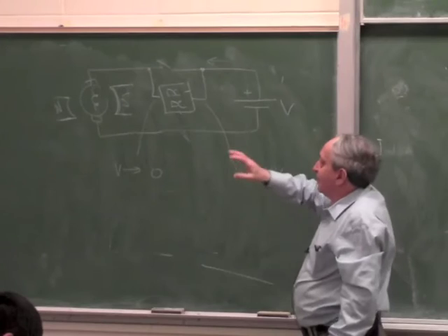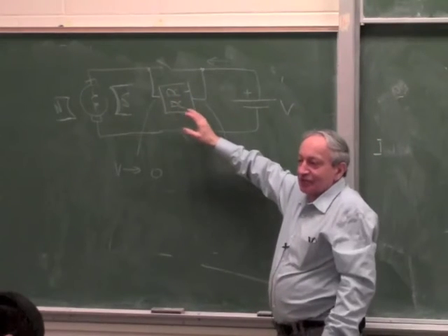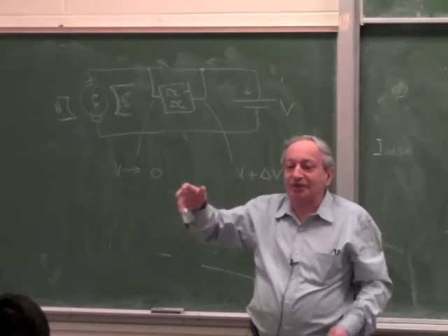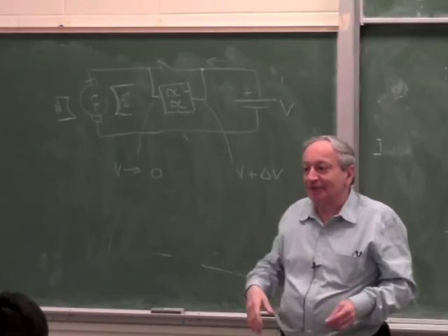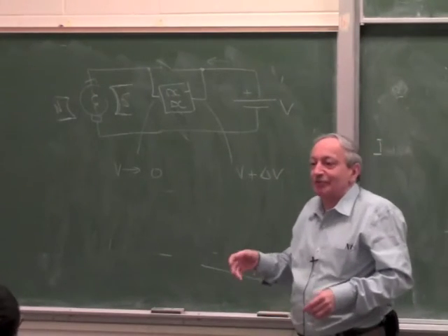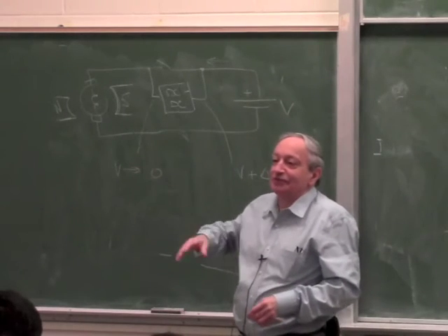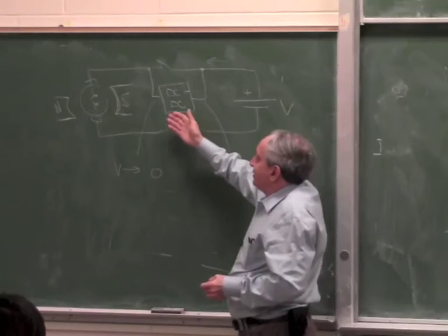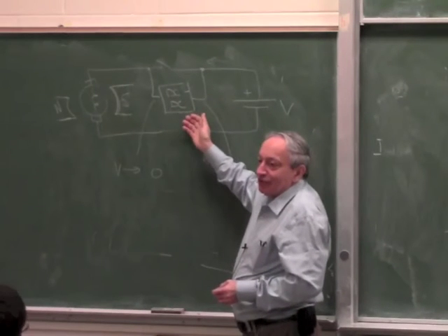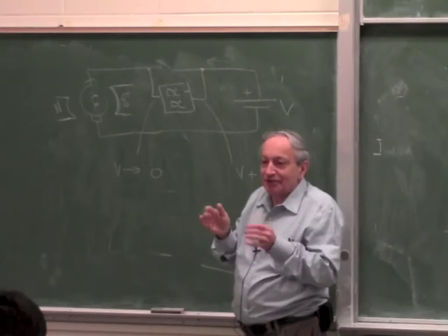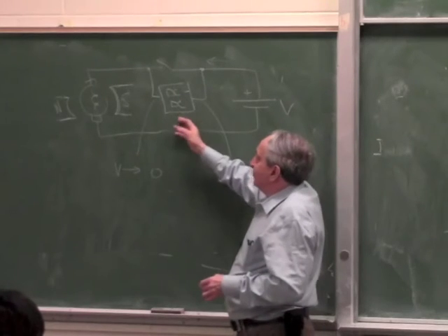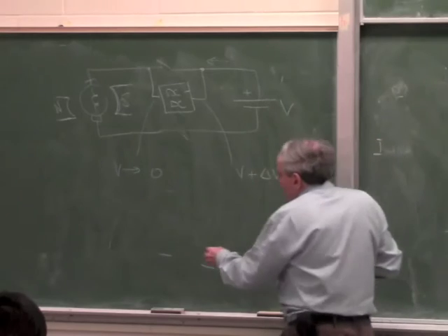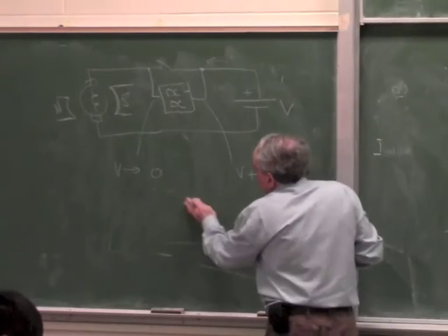Now, physically how this is done is outside the scope of this course, but think of any switching power supply which can take any voltage, like your computer. The power supply can take anything from 90 to 280 volt. It also gives you 12 volt. So it's the same thing. You can do it by DC to AC, then a transformer, and change the pulse width modulation. You can even do it without a transformer, and that's the way it's actually done, by a smart idea.